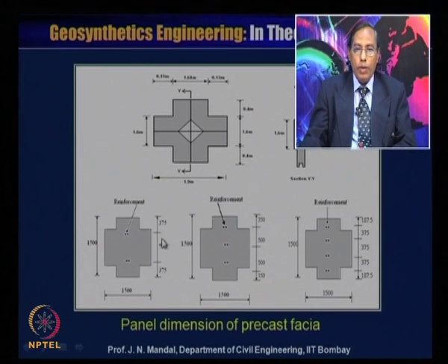Then this is 375, then upper will also be 375. So, entire will be about 750. So, spacing is almost 750 millimeter. So, 750 millimeter, 750 millimeter, like this, the spacing remains constant. Also, different manufacturers have come up with different types of prefabricated spacing element.